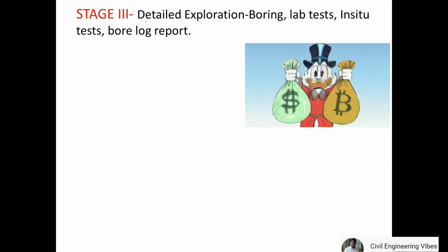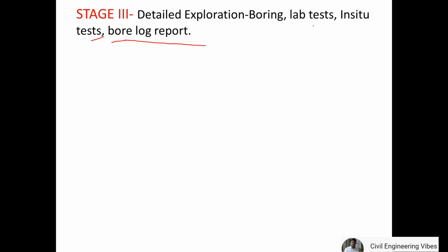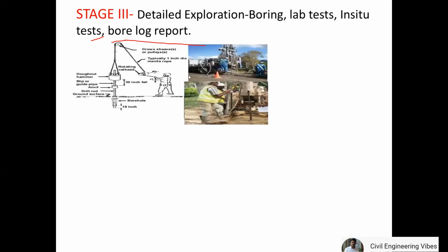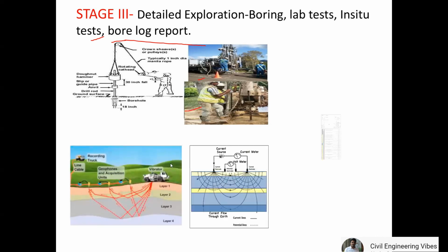Now coming to stage 3. Detailed exploration is the supplement to stage 2. Stage 3 investigations are performed in the case of heavy loads, major structures, large engineering works, costly foundations and complex behavior of subsurface, from stage 1 and stage 2. Field tests are performed to obtain parameters for design, and bearing capacity is known.